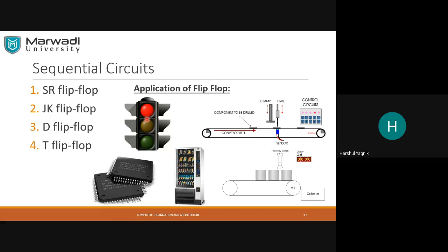So when we design this algorithm, the algorithm will need a counter circuit, a counter IC, to calculate how many clock cycles have happened. We need an additional clock circuit to generate a reference clock. Then we set up a counter circuit which changes its value every 1 second. And then we need to design a logic which will generate 3 different signals depending on what the previous result is, right?